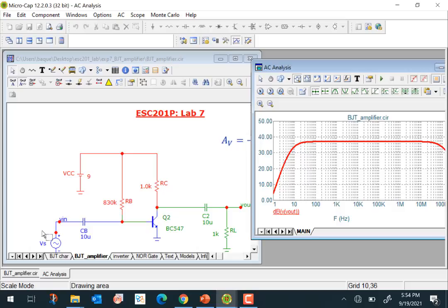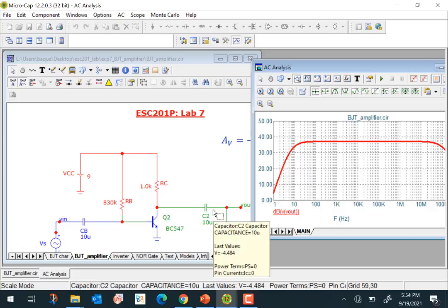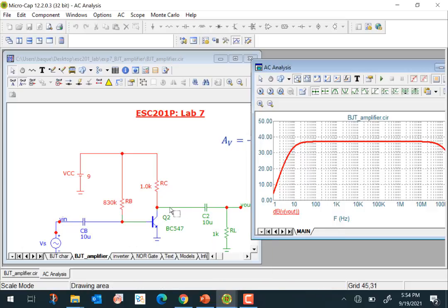If there is a component at 100 hertz and there's a component at 1 kilohertz, and the 1 kilohertz component is higher in magnitude than 100 hertz, we would like that kind of a relationship to be preserved. We want the entire thing to be magnified, but the relationships among different frequencies, we would like to preserve that. So that would happen in this particular region here, right? So this is where the gain is independent of frequency. But in an amplifier like this, the gain is falling or becoming frequency dependent here.